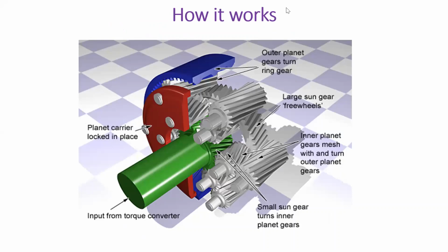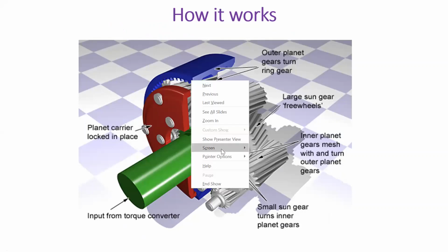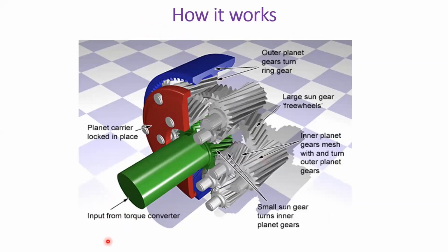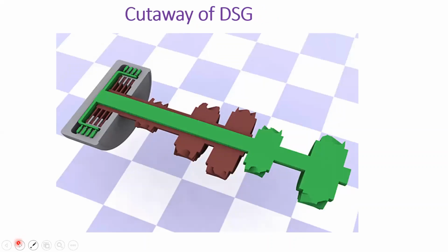And when it comes to the compound gearbox or the planetary gearbox, the input is coming from the torque converter, and you also have a similar arrangement to what we have seen in the case of your normal automatic planetary gearbox. In the case of the compound gearbox, as the name indicates, you have the composition of both the small sun gear and the large sun gear, which will get in contact with the planet gears, and accordingly the transmission is going to happen with the help of the compound of both the small sun gear and the large sun gear.